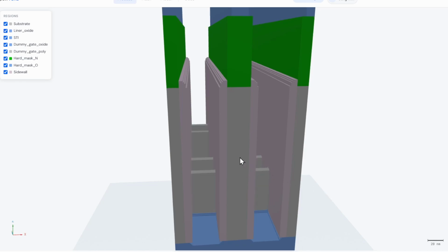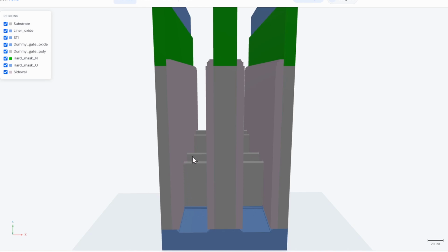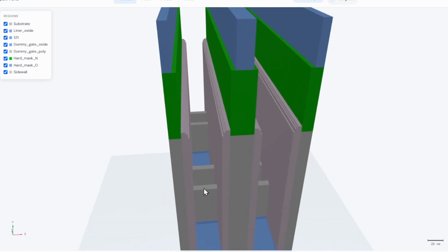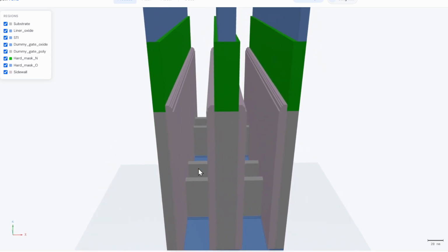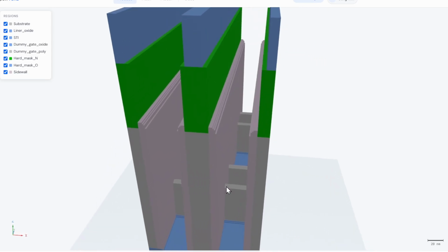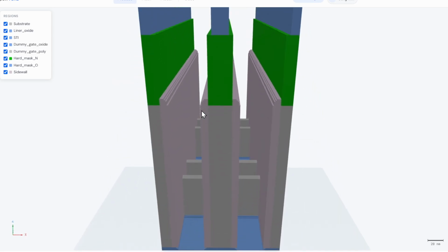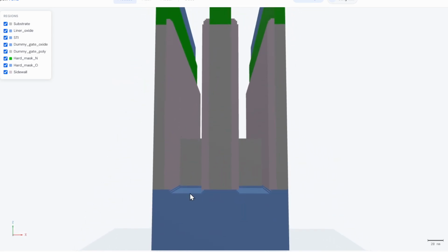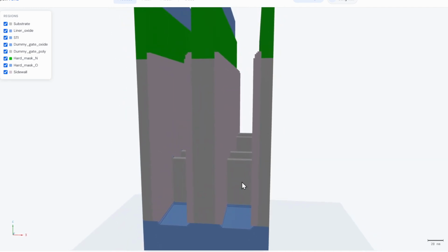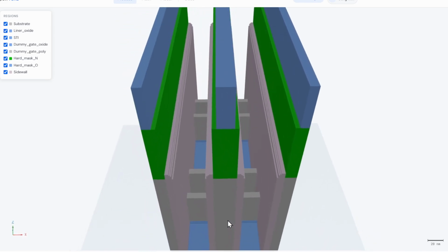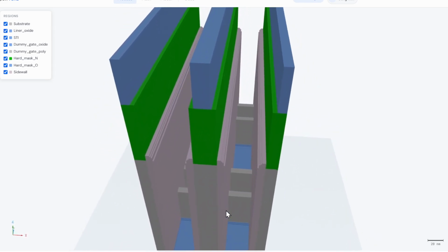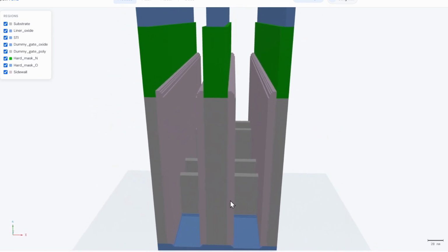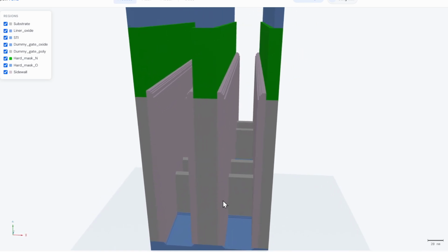Now you can find that this dummy gate oxide is etched away, and now the silicon fin is revealed here, and there you can see these gray layers are found, and slightly this STI part is also etched away, but it's completely okay. So now we are ready to do certain parts of the source and drain formation.